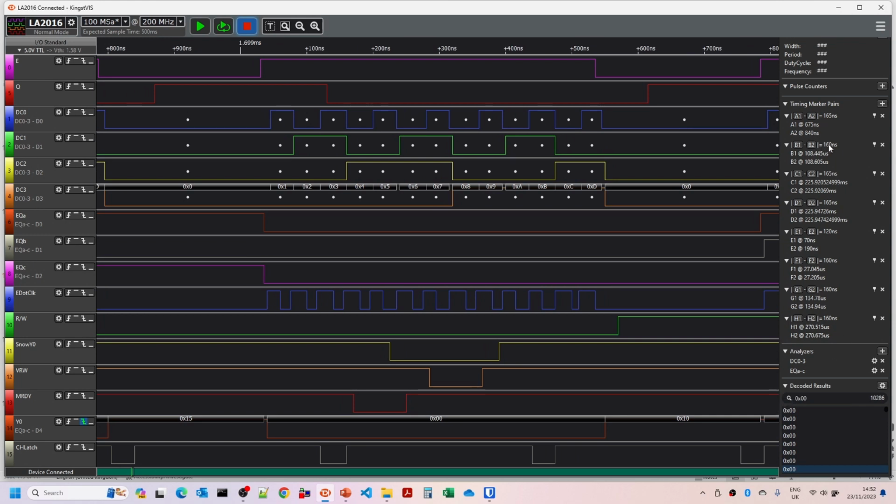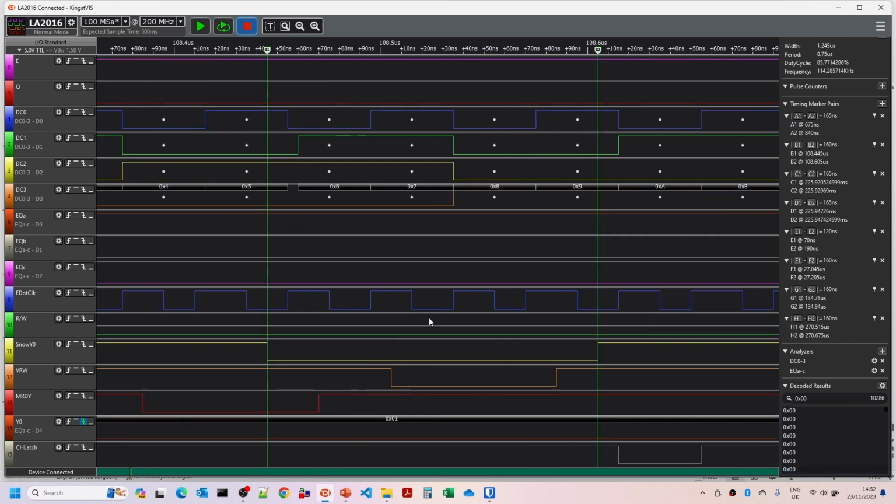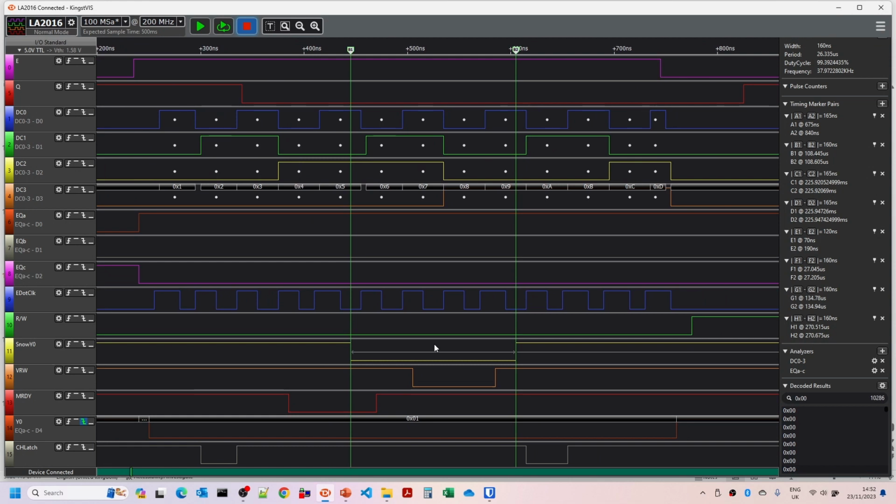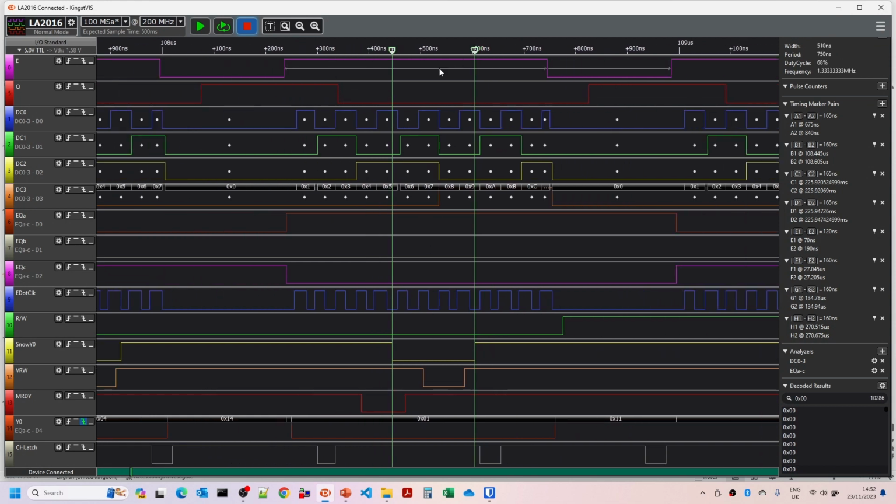So now if I go to the number 1, you can see for number 1 we've still got the stretching of the E clock signal. You can see below it that the Q signal I've added here also stretches by a similar amount of time. Then we have the dot clock combined with the E signal here, which is what's used to count the number of dot clock cycles we have from the rising E edge.